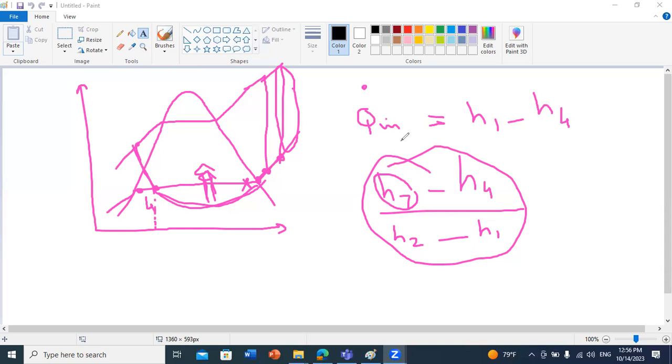Well, I understand maybe that if I just give you a refrigeration cycle, you'll not be able to draw it on your own. But if I give you a small description, some hints, I tell you that in refrigeration cycles, we extract heat from a cool temperature and reject heat into a higher temperature, and we provide work through a compressor. By just giving you this, you'll be able to draw the TS diagram. And how to work with enthalpies is the same method, you use the same tables, etc.